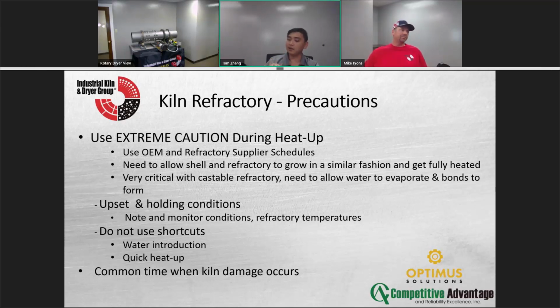But on a dryer, if you've got a direct heat where you've got the combustion chamber, that typically has refractory also. That causes issues if you don't give it time to heat up and cool down. Right. That's why this is a critical spot. Otherwise, you just get a lot of issues.